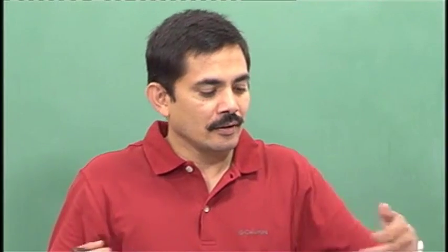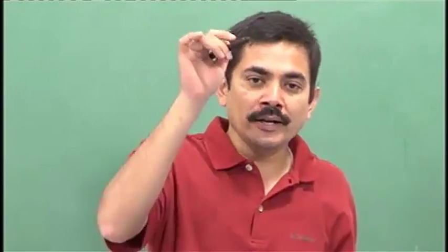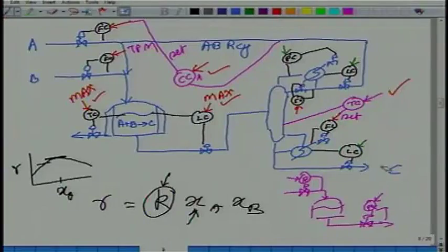Before some constraint gets hit and you start getting contaminated product. So the fundamental thing here was, the moment you put a product purity constraint, fixing A and B independently cannot be done. If you did not have a product purity constraint, you could have fixed A and B independently. Whichever was excess would have come down the bottoms. Do you see what I am saying? So what is your production objective? That also fixes that set of 6 degrees of freedom, which makes sense. If you want 99.9% purity in the bottoms, fixing A and B independently does not make sense. It is guaranteed to violate material balance for the whole plant.